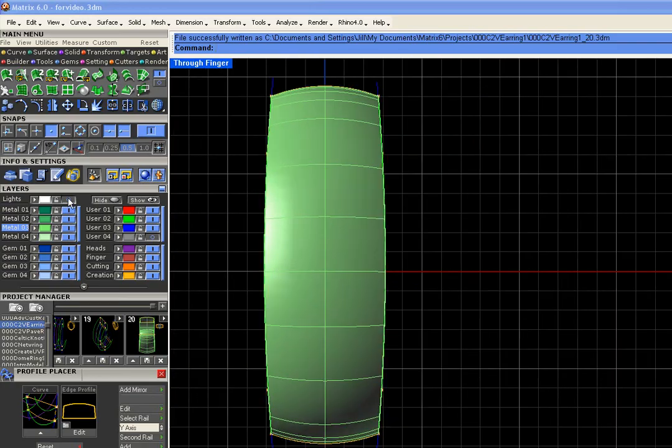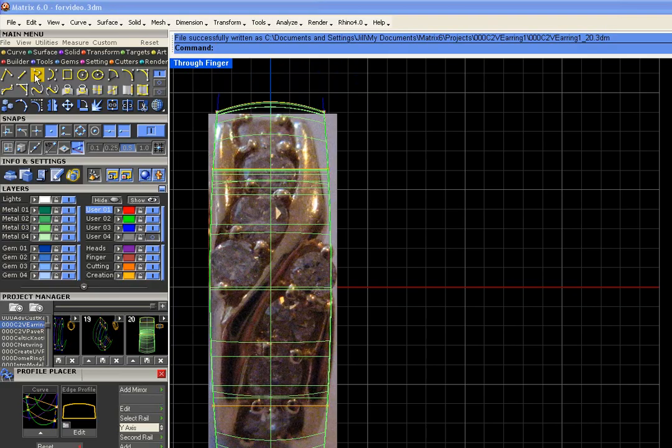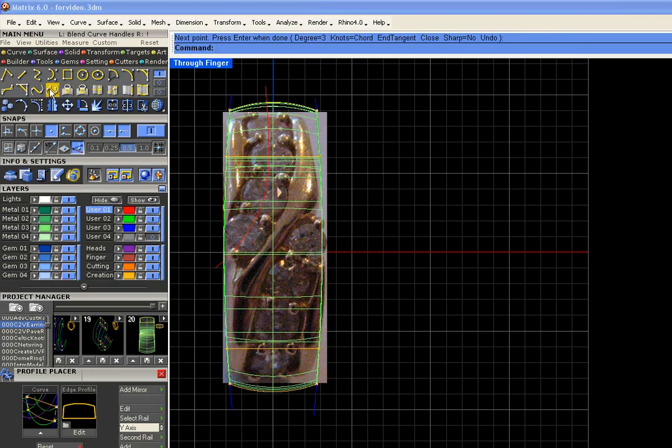Right? We can turn back on our picture. If it's out there, there it is. Unshade the model so we can see it and make sure project is turned on. And now we're going to just grab the interp curve tool and draw this shape straight through the model for the gems. Okay, we're going to run project and project the curve onto the surface.